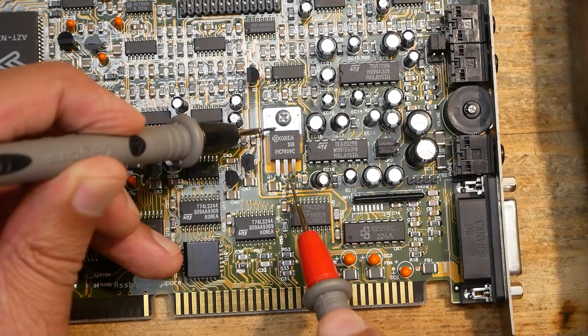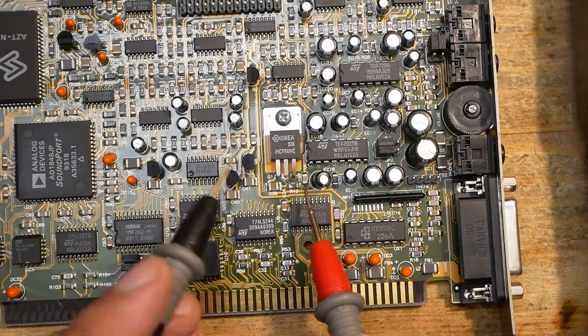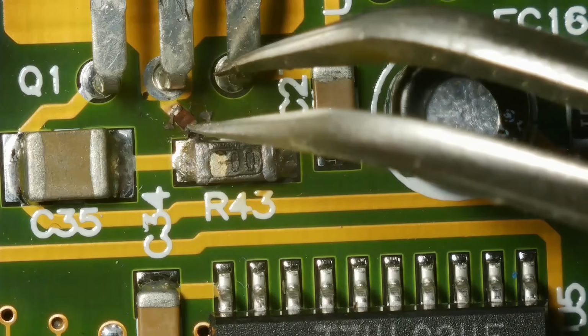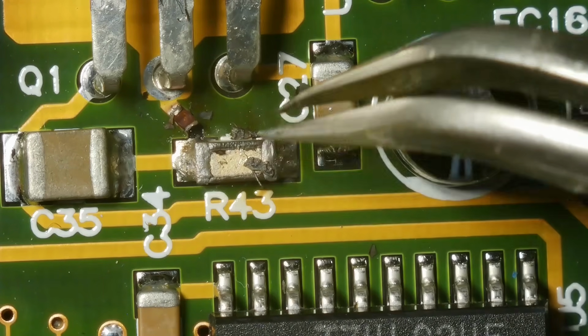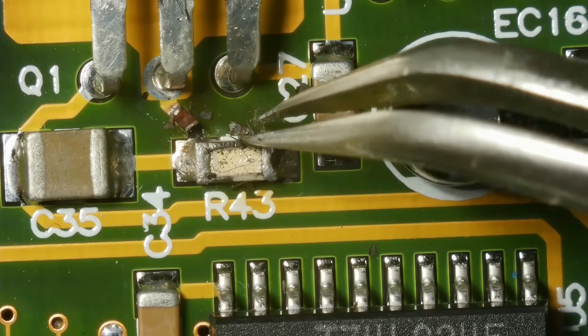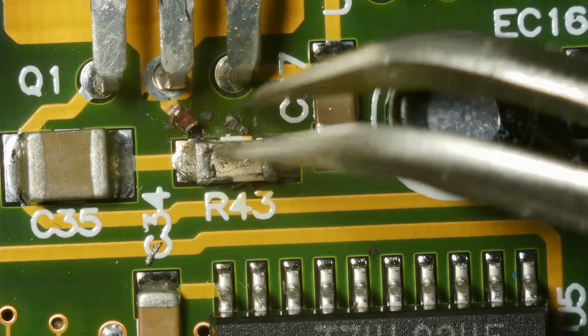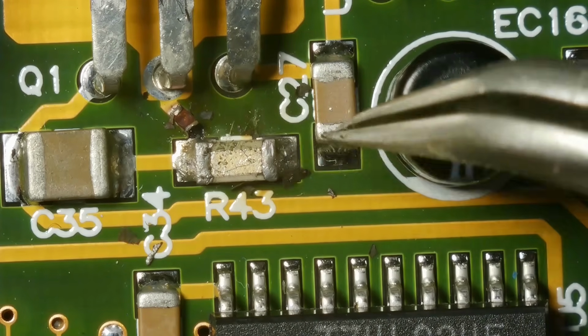This is the second card with a similar damage. Here, as I said, a ground trace has burned through. Let's take a look under a microscope. Here it is, the trace from the resistor is toast and lifted. The resistor has obviously suffered a serious overheating. I measured it previously and it seems to be still conductive, but the marks are all burned off.